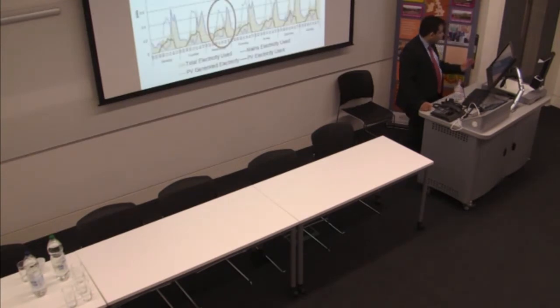But mostly, solar PVs did work in these communities. What's also interesting is we were looking at self-consumption, because it is no longer just important to have generation. It's also important to know the time of use: when is it used, not just how much. We found that it ranged from 15% to 68%. That is how much of the PV electricity that's generated is used in the house versus how much is exported. That's very important for smart grids, smart networks, smart appliances. The average is 45%, so we could say some of the assumptions in SAP, which assume 50%, are fine, at least here.